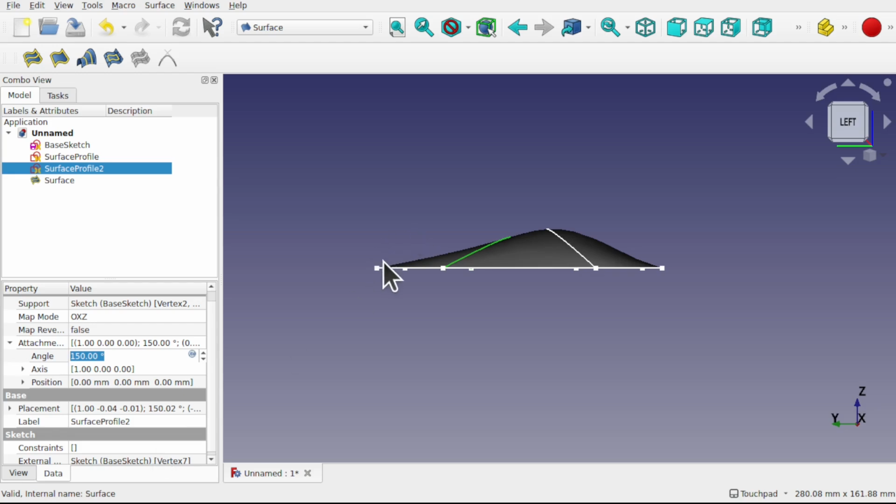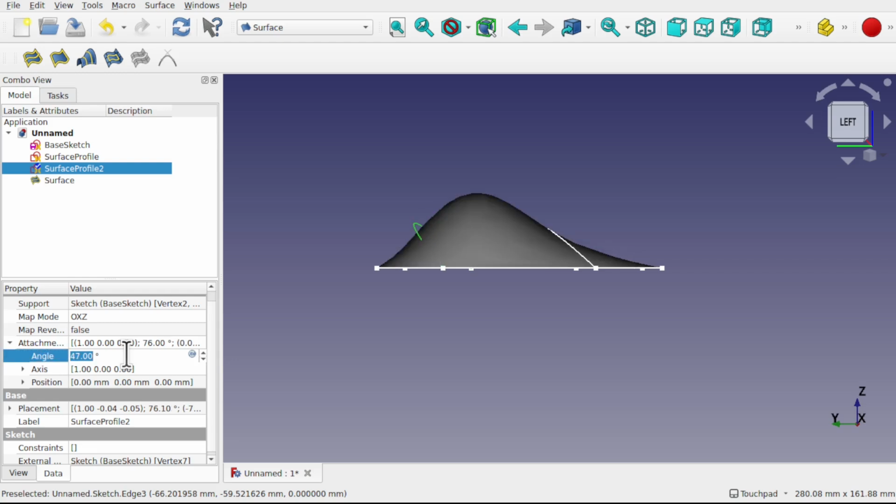Notice the continuity of the surface. So basically we've got an arc between these 2 points like so. And the constraining edges we've added constrain the arc between these two surfaces. So we change the angle right up to say here, you can see that the surface is being constrained, but it's still trying to make an arc between these two. So I'll bring this right over so it's in this angle, hit Control R. You can see how that surface is being unconstrained, so it can just produce the arc that it wants to produce.